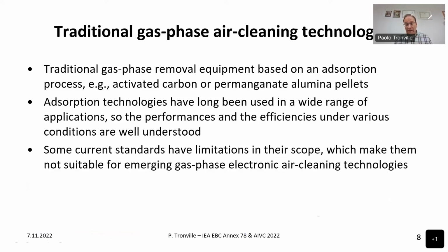As I said, the current test methods were developed having in mind the traditional gas phase cleaning technologies, so mainly activated carbon or permanganate alumina pellets, fibers or foam, adsorbents that are able to capture the contaminant through physical or chemical phenomena. These sorption technologies have been used for a long time. They have some pros and cons. However, for sure, the current standards have some limitations because they were designed having in mind these types of technologies.